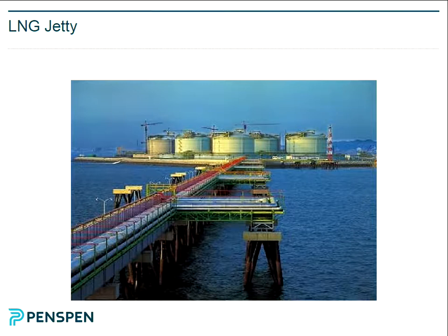So not only is it a heavily insulated pipe, but it also has potentially an enormous axial load. So you put these loops in to stop it effectively generating a very, very high tension. So that's a very special case, an LNG pipeline.